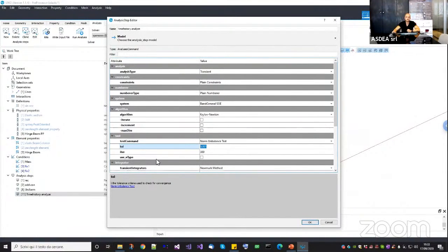But it basically depends on what you're modeling, because if you're modeling a very small part where a moment of 0.01 is very large, then this one is not good for you. So it's always based on the model and the units that you're using. Keep in mind that this is a number that for you is negligible in the vector you're looking at. For me, 0.01 for any quantity in the unbalanced vector is small. But it depends on the problem, so there is not a unique number.